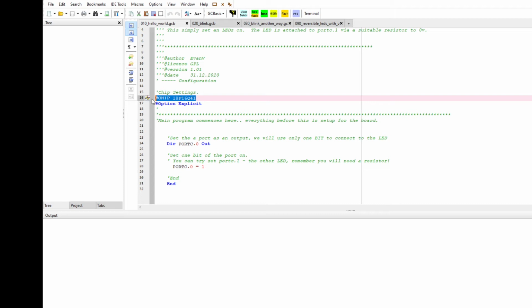As we move through the week, we'll open up those demonstrations. And then the third line of our code, we're going to set the port to out because we need it to be an output, and then set it high by setting it to number 1 because it's a binary port. 0 is off and 1 is on, and then I tell it it's the end of the program.